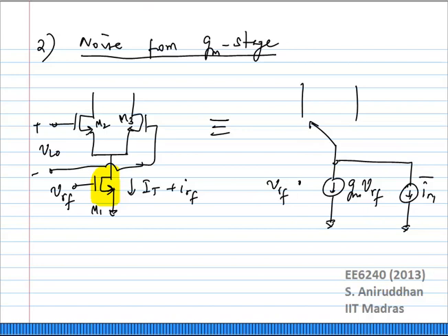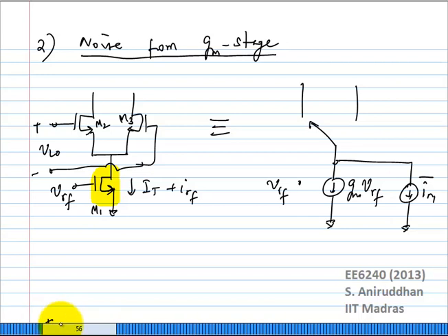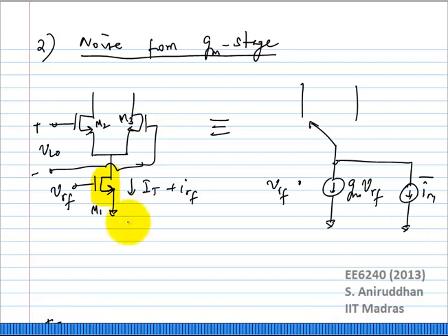It could also include the flicker noise also. We are going to see both, what happens with both. So as before, we will say that IN1 gets modulated by S of t due to the switching pair.